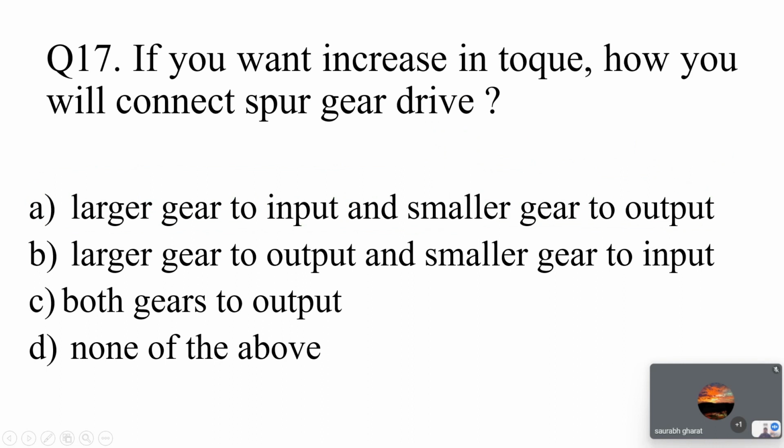Question 17 is like that, but right now we want increasing torque. Increasing speed and increasing torque are different. Okay, you must know this part: increasing speed and torque are different. So for increasing torque, you have to calculate now. Torque means you need a larger gear to get the torque. What is torque? Force into R mostly. So for that you need more R, means more diameter, means more size, means larger. So where you need to connect, you need to think. Okay, and after that I will solve this question. For right now it is for torque.